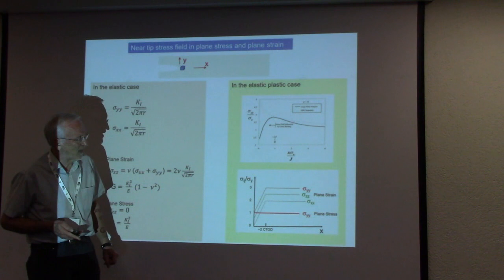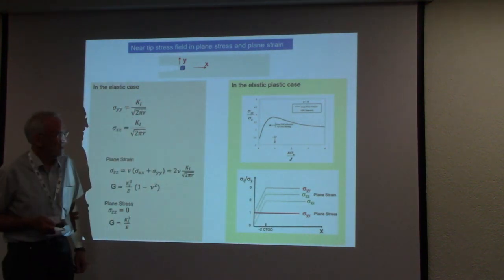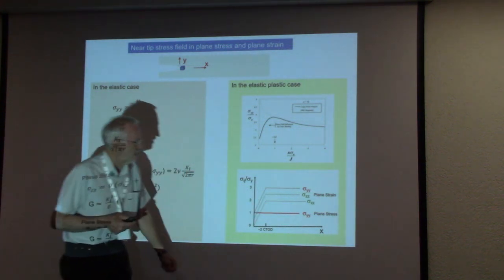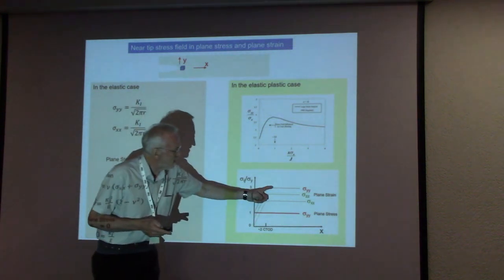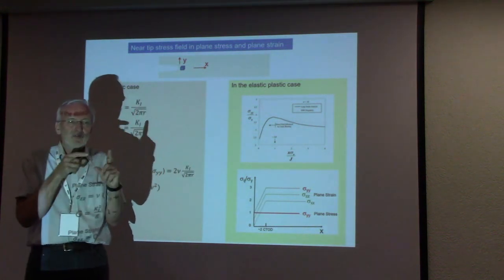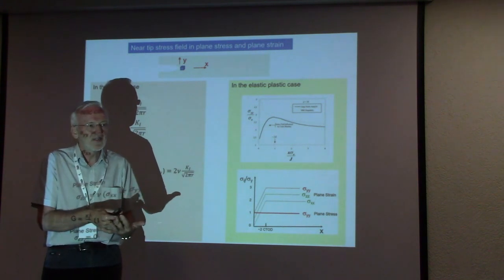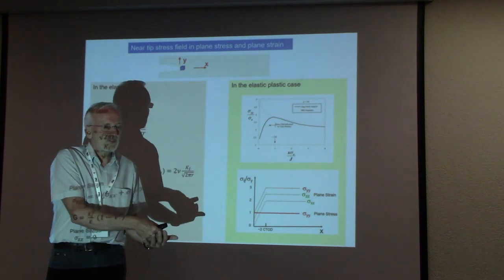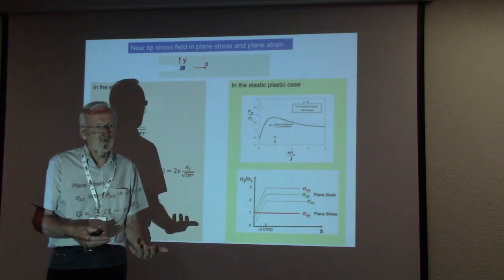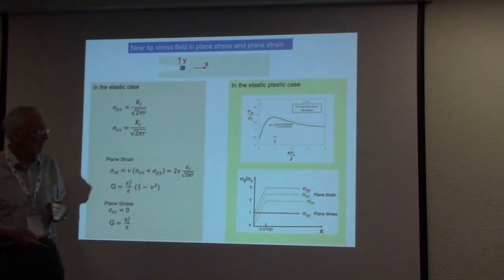And in plane stress, the stresses are significantly reduced to about the yield stress. It is very simple from the consideration. And this enormous difference, 3 times the yield stress, between plane strain and plane stress makes this enormous difference between a plane stress dominated fracture experiment and a plane strain dominated fracture toughness experiment, which happens often in thin samples.